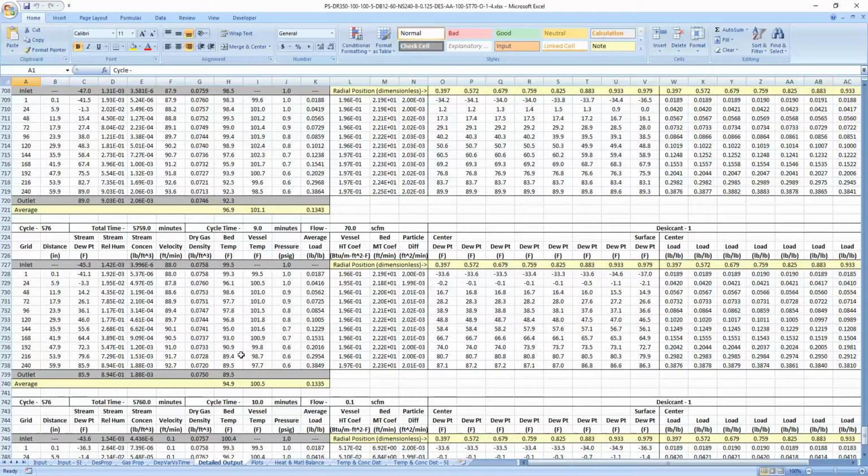And it's very easy with this simulation to see what happens if you, for instance, reduce or increase the amount of purge, and not only the importance on the dew point performance, but also what happens as far as the temperatures in the bed. Not that that's necessarily something that the customer is concerned about, but that the dryer engineer improves his understanding of the physics of what's occurring.